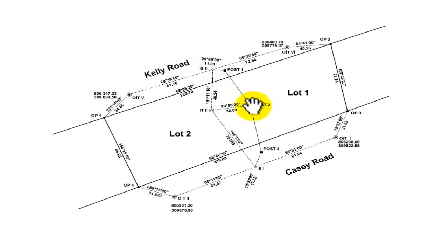Post 2 will become a boundary mark, and we will be placing pegs on the intersection of the fence and the boundary, a peg here and a peg there. Just how we go about it: first of all, we have two marks along here, for which we have known bearings and distances, and ties out to some old pegs which define this boundary.